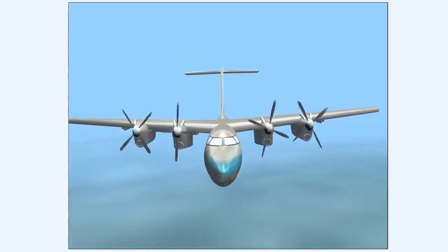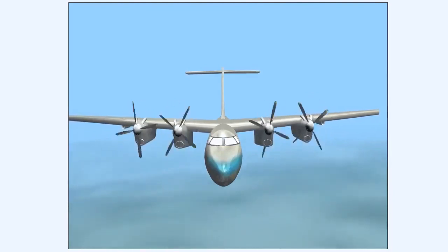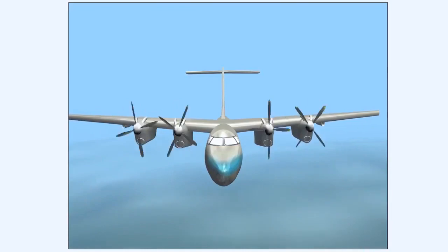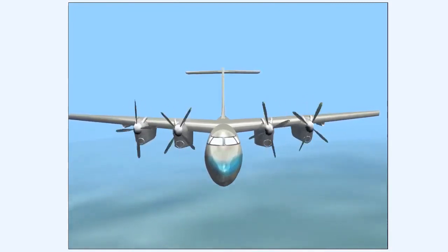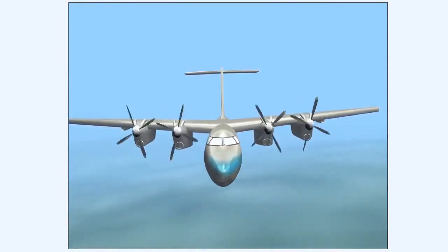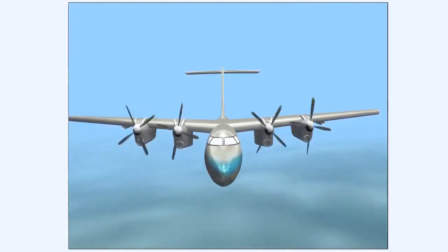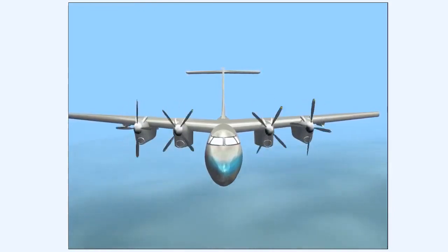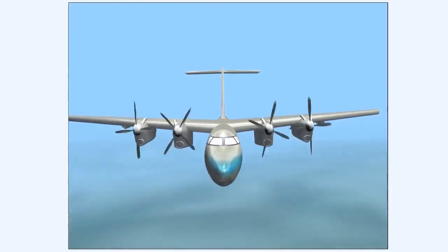Electromagnets in the head of the rotating assemblies of the propeller control units of each engine are used to generate an RPM signal. An aircraft fitted with such a synchronization system will have a designated master engine, and other engines will be specified as slave engines. The signals from the propeller control unit of the master engine and those from the slave engines are sent to a control unit where they are compared. With the synchronizing system engaged, any RPM differences between the master and slave engines will be sensed in the control unit.